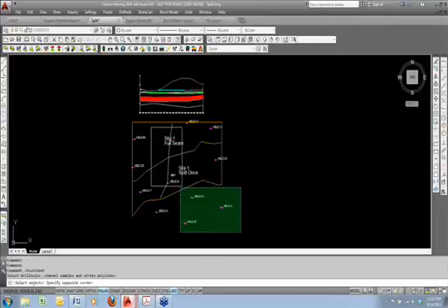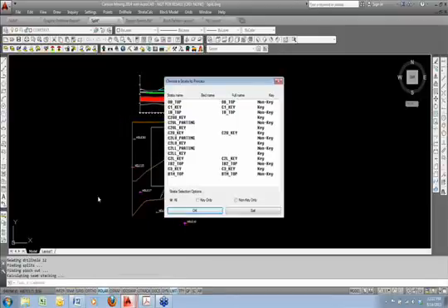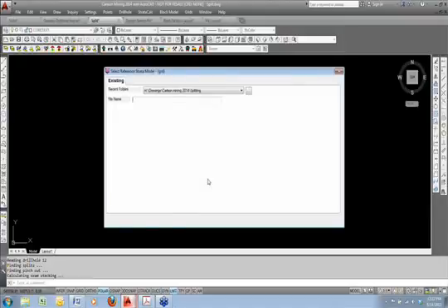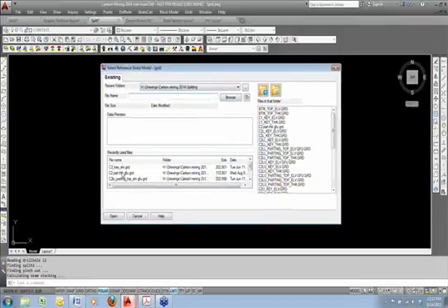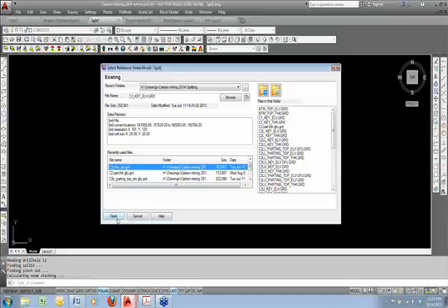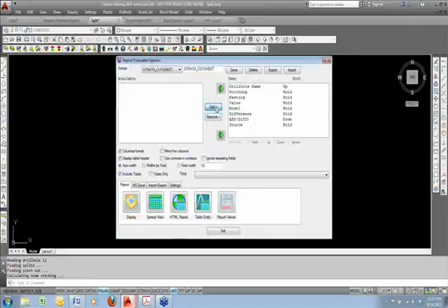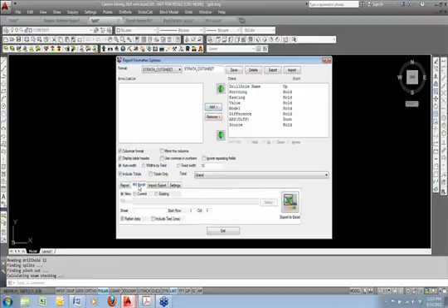So I'll choose all of the drill holes. And let's go ahead and choose that same C3 seam. And we'll just consider the bottom elevation. We'll compare that with the drill holes themselves. Select that seam. Here's the C3 elevation. And then the report formatter appears where we can then move things from left to right. We'll move them all over, and we'll take this out to Excel just to view the data.